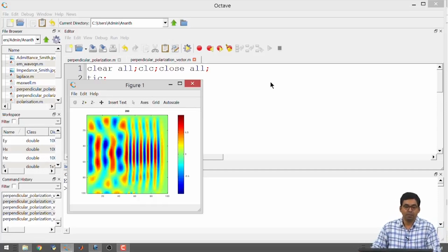So manipulation of boundaries is very important. In the case of transmission lines, we had made use of what's known as absorbing boundary conditions. One could extend the same concept there. So people use these conditions just to have a cleaner visualization without multiple interferences in the first medium. So you could have absorbing boundary conditions over here. We will look at that a little later because now it's an overkill.